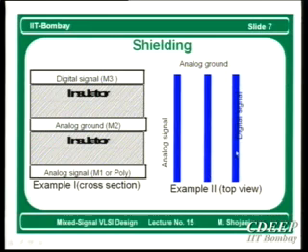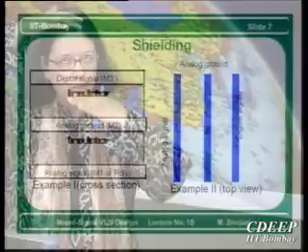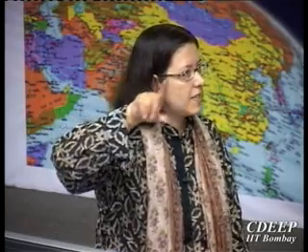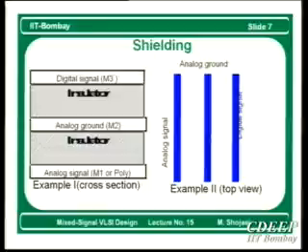Or for example, top view. If you look at the cross section, they are stacked, right? Metal 1, metal 2, metal 3. You may have all metal layers in one level, but still, metal has a thickness. Therefore, you will have sidewall capacitances which can be coupled to each other, and fringe capacitances. Therefore, again, here we do the same thing.